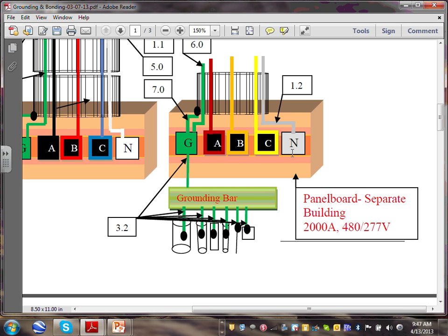If you're using single phase, you're looking at 4 conductors, right? 2 hots and a neutral plus the equipment ground conductor. But you can run 3 conductors if you don't have anything metallic between. For existing buildings though. Oh, for existing buildings. Yes. So you can't go build a barn or another shed and treat it this way. But you can have an old building sitting there and then run 3 conductors to it. It will be very hard to pass the inspector.